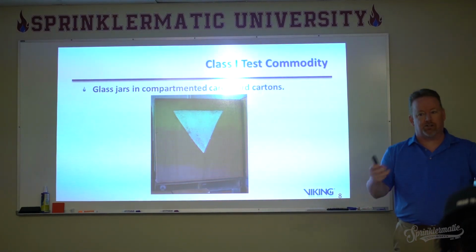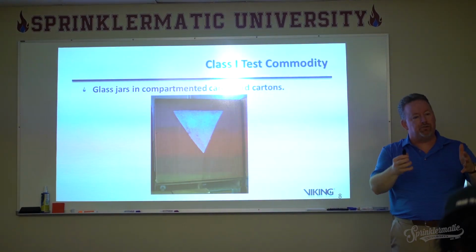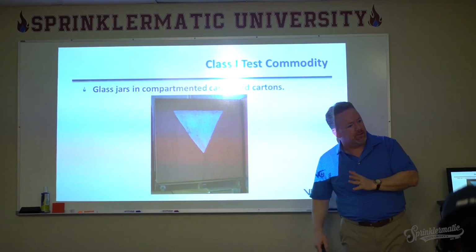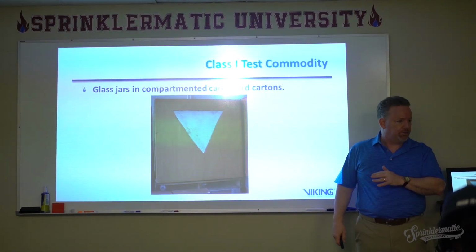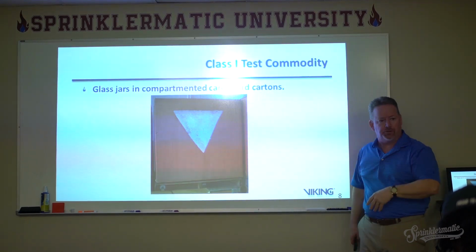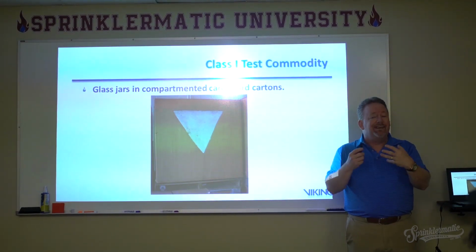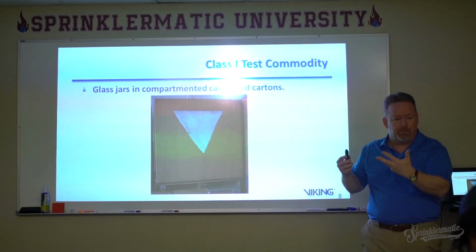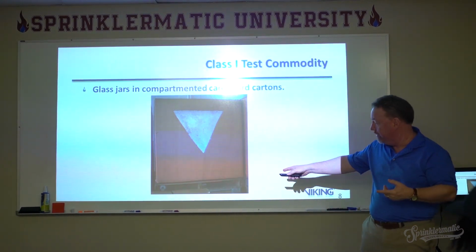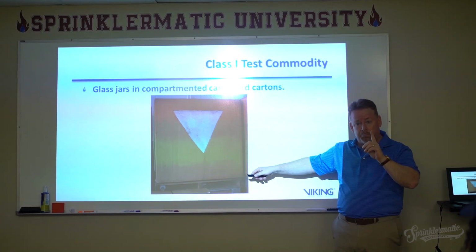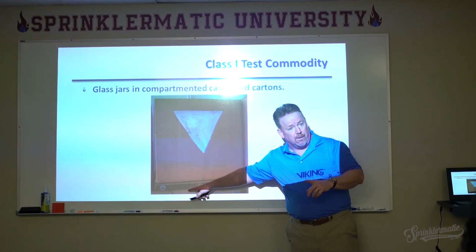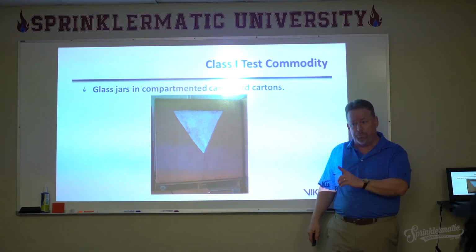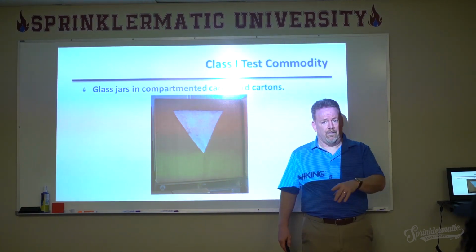Burn that commodity, determine its heat release rate, and use that as the test commodity to compare these other commodities to. So it's non-combustible in a single corrugated box. By definition, the single layer corrugated box was going to be the biggest challenge. And all of these, when they were tested, were placed on wood pallets, solid wood pallets.